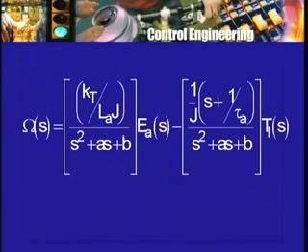And if you remember, the denominator gives rise to two poles of the transmittance or the transfer function in each case, whereas for the transfer function from the applied voltage, armature voltage, to the speed, there is no zero but there is only a coefficient Kt divided by La into J, whereas for the transfer function from load torque to the speed, there is not only a coefficient 1 by J, but there is also a linear term which corresponds to a zero.